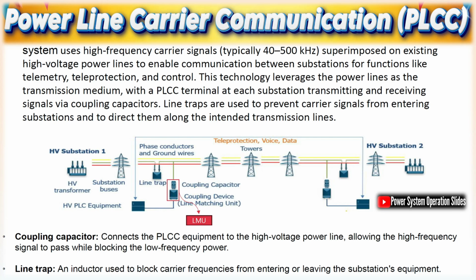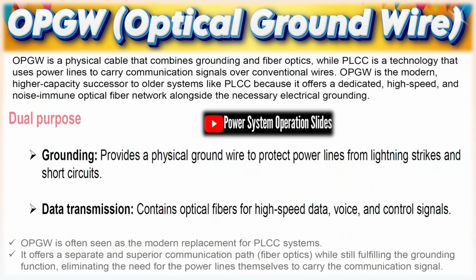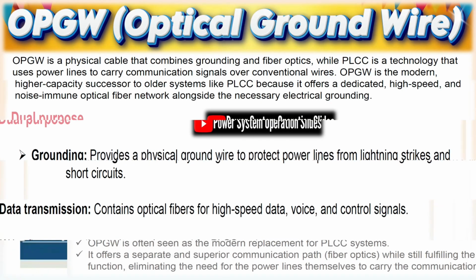Protection relays. Relays detect abnormal conditions and initiate tripping based on reliability, selectivity, sensitivity, speed, and stability. Their philosophy ensures fault isolation with minimal system disruption. Digital and numerical relays dominate modern systems.